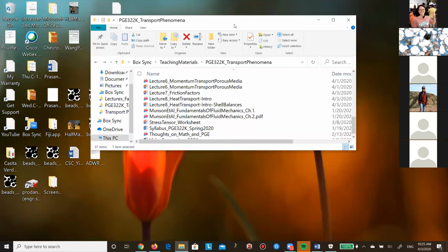This is not always the case. And what we normally evaluate with Reynolds number: at high Reynolds number, I have turbulent flow. So none of the equations necessarily apply. That is typically measured and correlated through experiments. And there's a concept called friction factor, which is essentially a factor that tells you how you should multiply your overall flux, give or take, to get the correct version for turbulent flow.